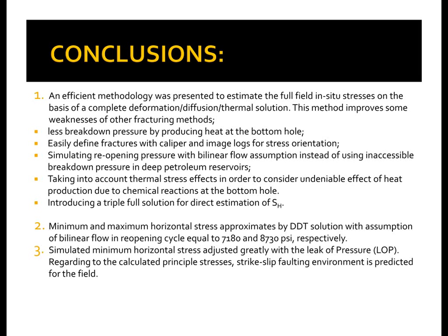This method improved weaknesses of other fracturing methods, including less breakdown pressure, by producing heat at the bottom hole; easily defined fractures with caliper and image logs for stress orientation; simulating reopening pressure with bilinear flow assumption instead of using inaccessible breakdown pressure in deep petroleum reservoirs; taking into account thermal stress effect in order to consider the undeniable effect of heat production due to chemical reactions at the bottom hole; and introducing a triple full solution for direct estimation of maximum horizontal stress.